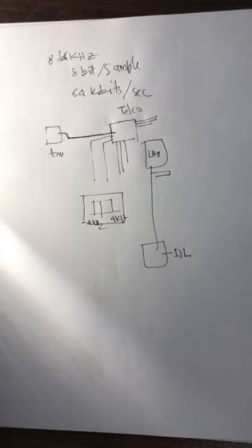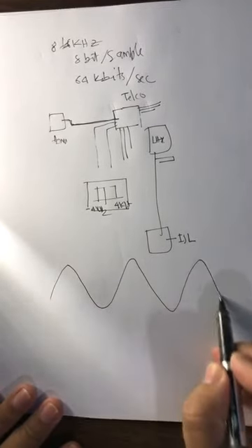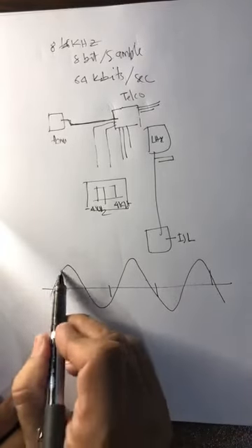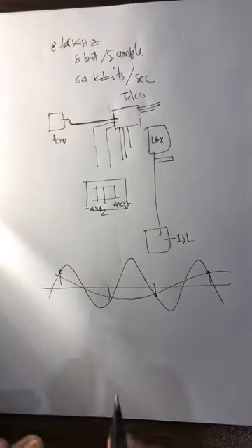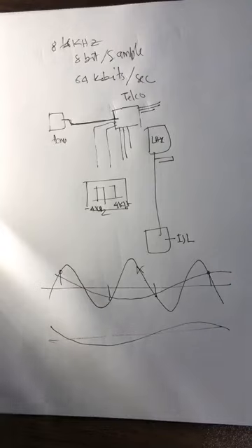And as you must have done a few examples, as Dr. Ali was telling me, about a sinusoid not being sampled at the right frequency. Okay, so this is a sinusoid. Instead of sampling it at Nyquist, you are sampling it at some other rate. So it will convert it into another sinusoid. And now you don't even have the knowledge that originally there was a sinusoid of high frequency. Absolutely no way for you to figure this out. So you lose that information, and all you know is that there is a sinusoid which primarily